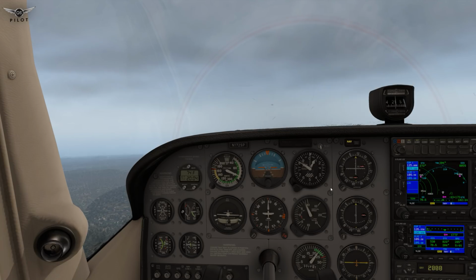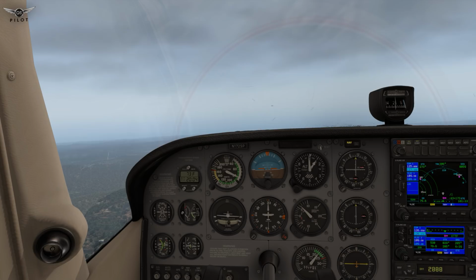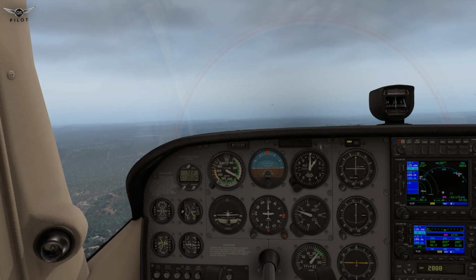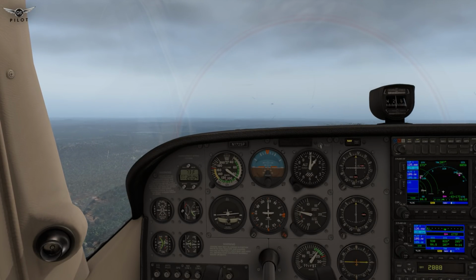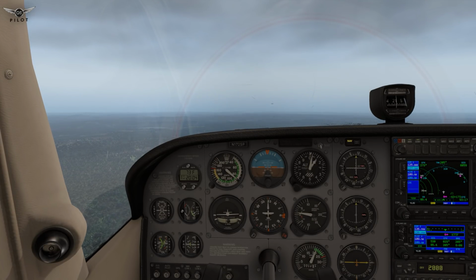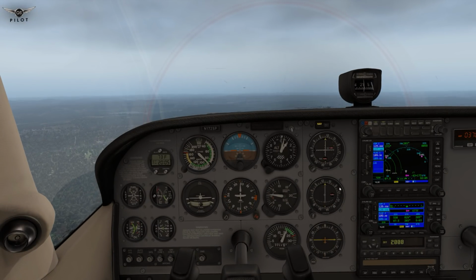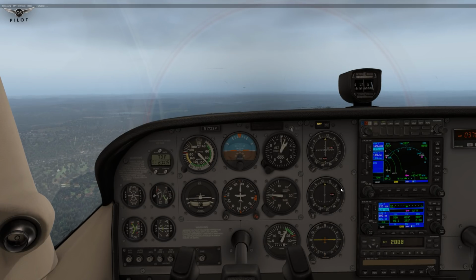All right, we're going to level off at 1,000 feet, and we'll call that our cruising altitude today. And we're about at 80 knots right now. All right, there we go. Let's go ahead and pitch down. And we're going to start reducing our speed. And let's go ahead and lean the mixture. All right. Before we begin our turn, I'm going to go ahead and Control Shift Z again. Okay, we've finished taking off and are now cruising.